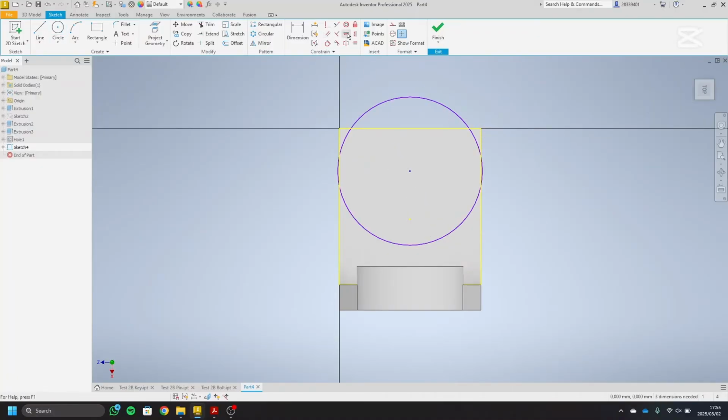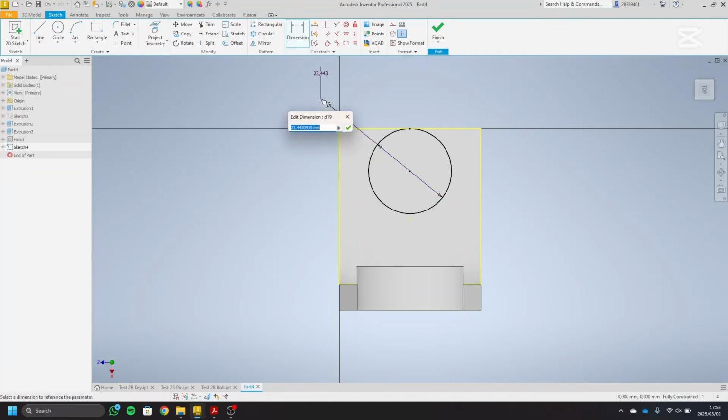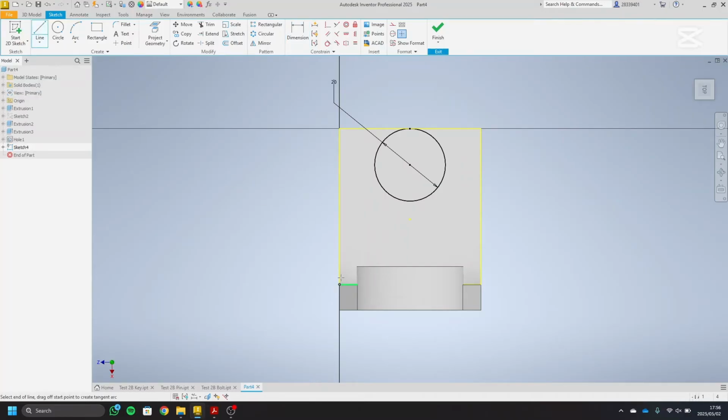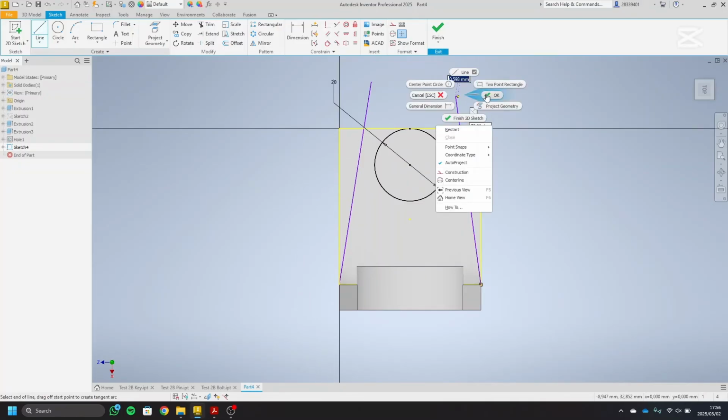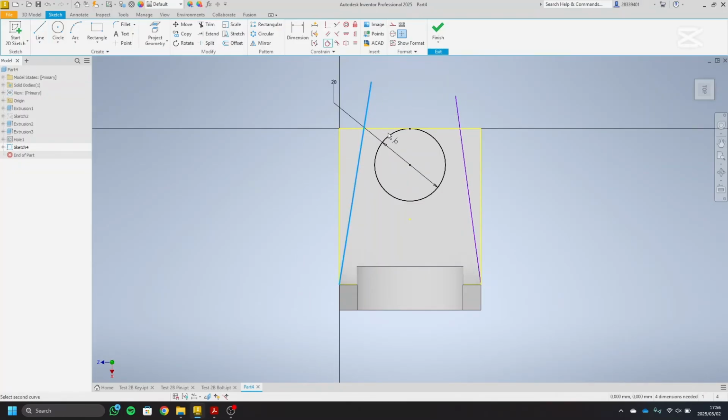that, and then we can just make this circle in line with these 2 pieces, just make sure it's in line, and then make this circle tangent to this point and give it a dimension of 20. Perfect. And then we can make these 2 lines again on either side, and then just make these lines tangent to the circle as well. Then trim up whatever is excess,